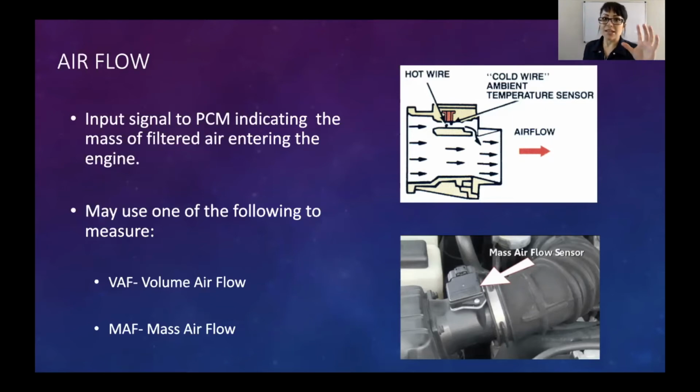Air density is key. Cold air is condensed, meaning it's going to contain more oxygen. And if you really want to know, the key to horsepower is not just more fuel, but we also need more oxygen. The limiting factor is oxygen. We can always add more fuel, right? We can always add more fuel. The computer can make changes on the fly to give you more fuel. What it has a hard time getting is oxygen.